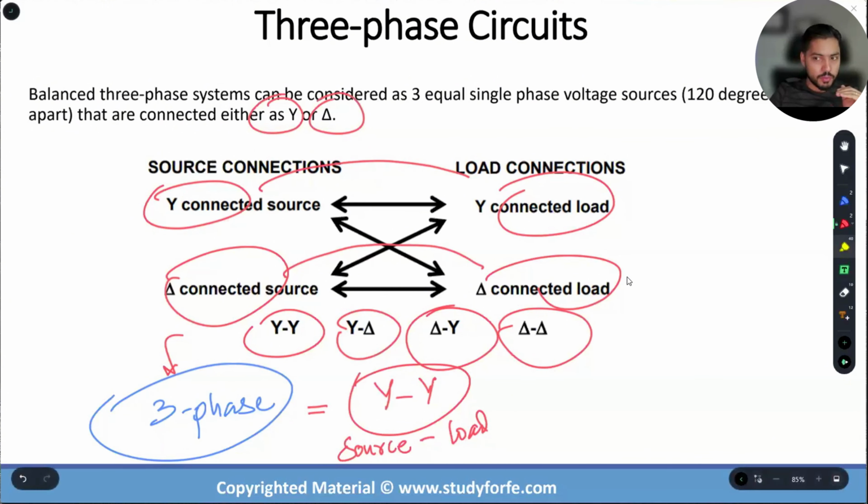But it all starts from your understanding, appreciation, and realization that three-phase circuits must be solved, especially when you're doing them on the exam, pen and paper, with calculator. They should always be solved in a YY configuration. If it's not in a YY configuration, nothing else matters. The first step is to convert it into a YY configuration. Is that clear?